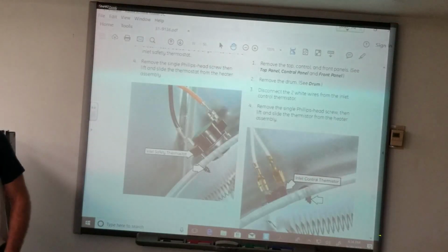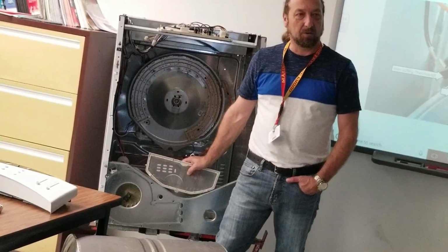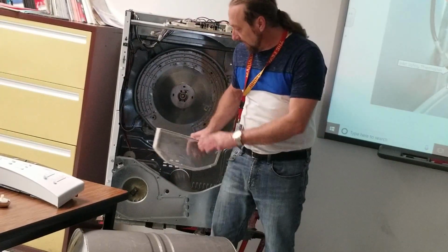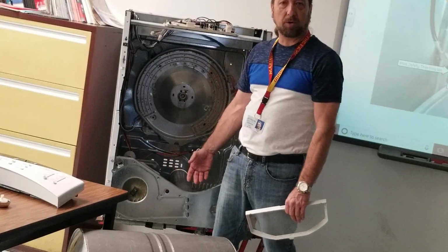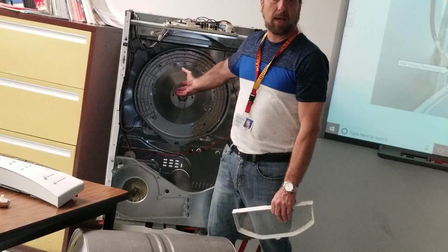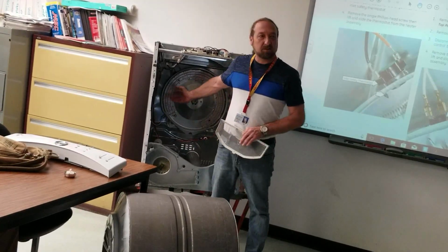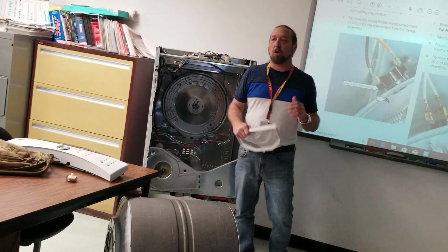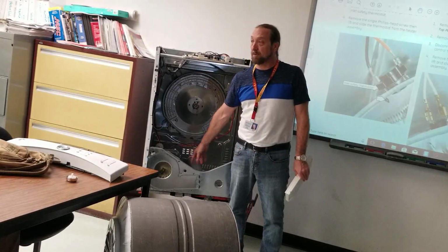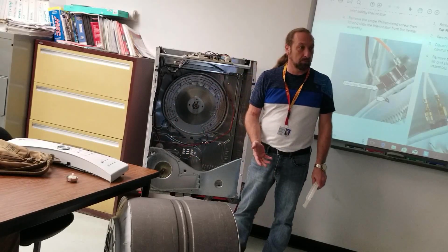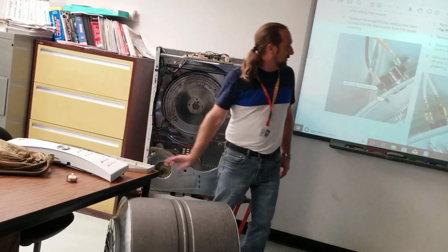If the customer doesn't clean this filter out, and it's sitting right here, what's happening to the airflow? Blocked. It's not flowing. And we have a thermostat right here and a thermistor right here, but if I'm blocking the air coming in the fan, this thermostat will never see how hot it is. And if I block the airflow here, I don't have airflow over my heating element, and I need to have airflow over it. If I don't, that element gets so superheated it bends and it breaks. So these controls on the heating element itself are almost always there just for safety. That's because if we have an airflow problem, the controlling thermostats that actually control the temperature we want to dry at cannot see the heat. So they cycle or they shut off based on that safety device there. Okay? So let's move on down.